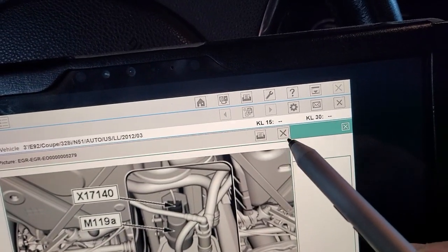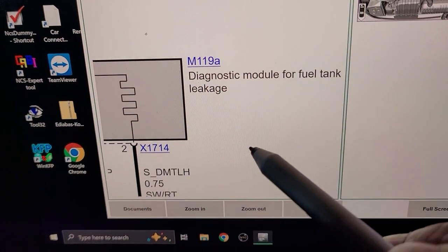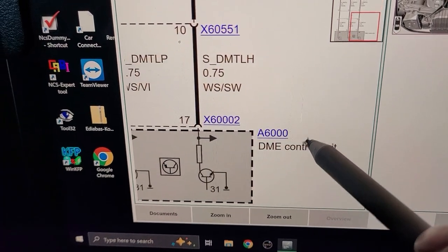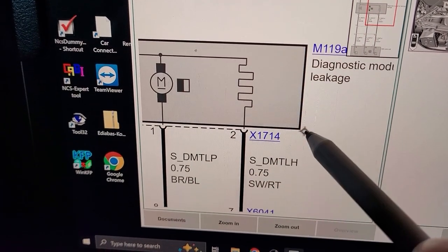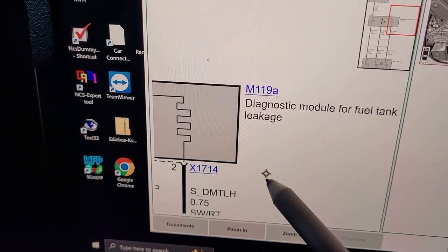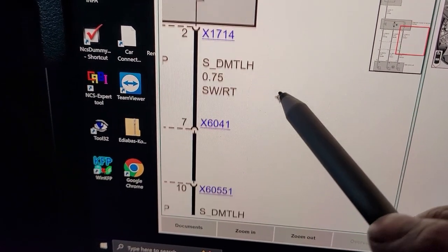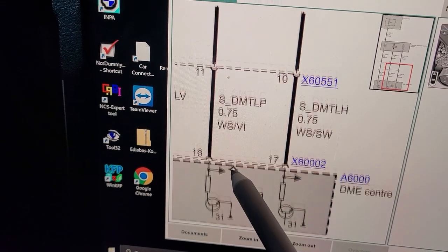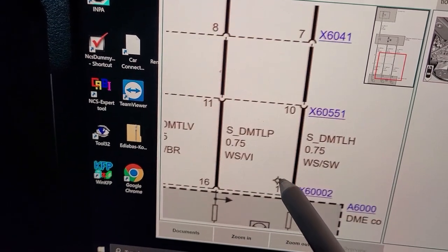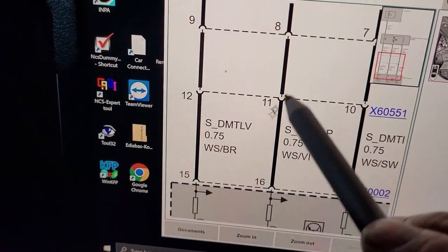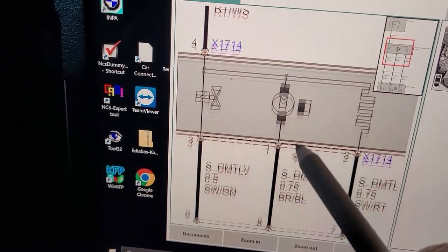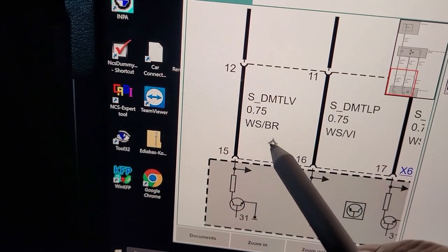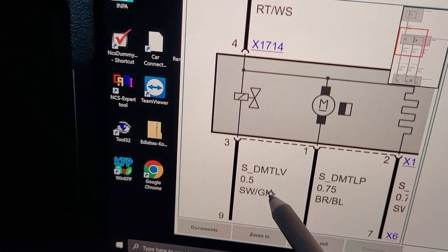Okay, then let's see, then the rest of it, and it goes one wire, so from this part, it sends a wire directly to the DME, and you need to check number 17, number 16 wire plug, and if you can't find a problem, I think we're not gonna have to go that far, but now you know.